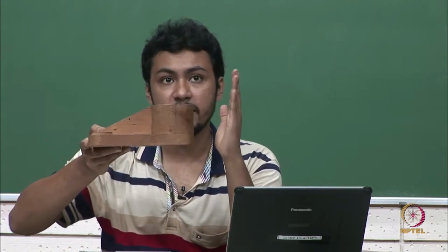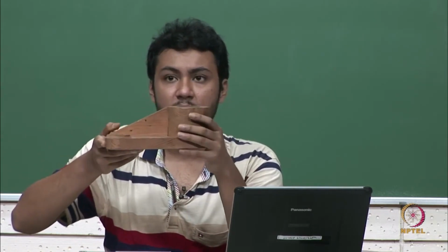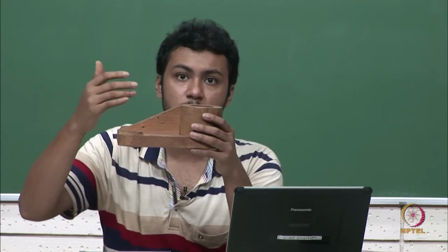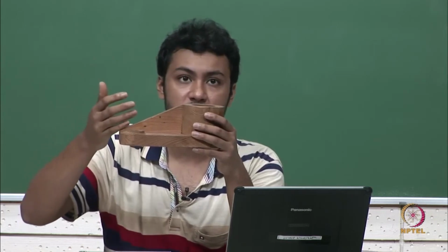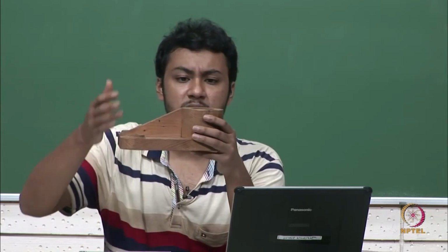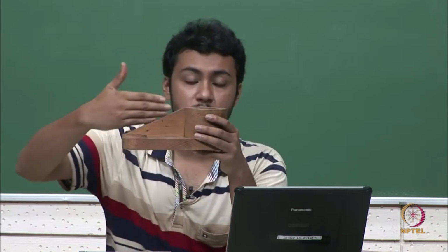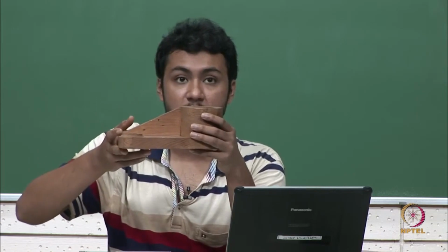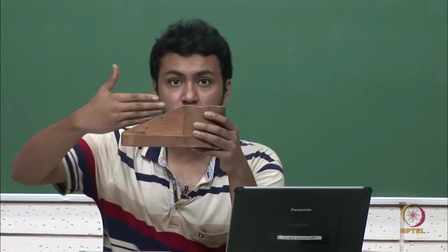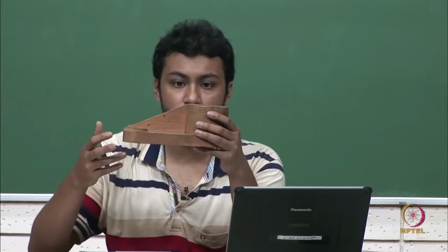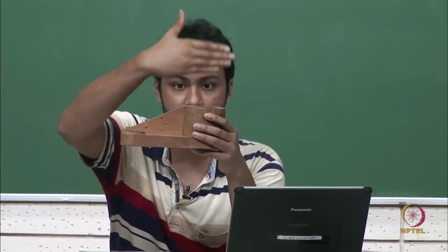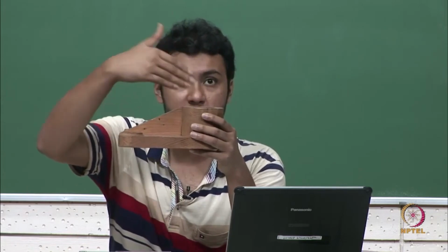The section rule is actually, after sectioning you should be able to understand most of the features, the internal features in most cases. So, this time we have chosen this cutting plane, so that we know what is the internal feature of this area, and after cutting what we will be looking at, I will show you, but first I will draw the cutting plane. The cutting plane is this vertical plane that I have to show in the top view, I have to represent that.